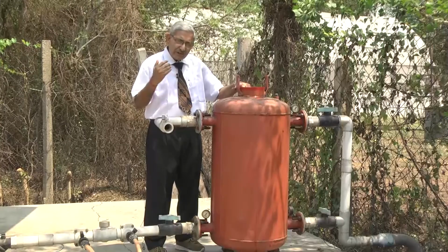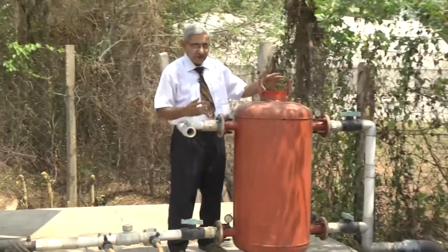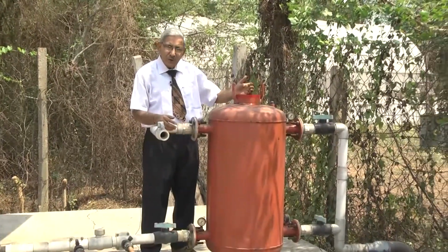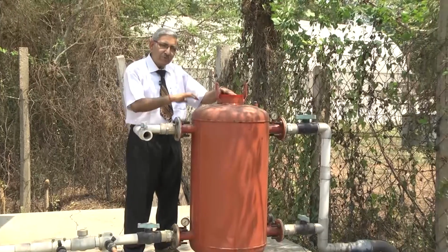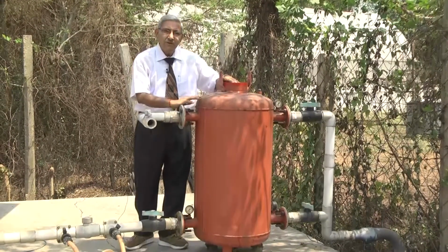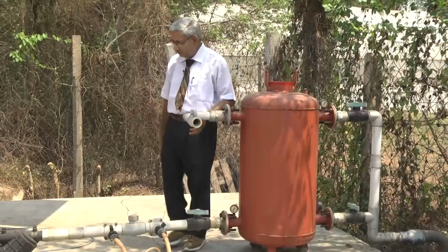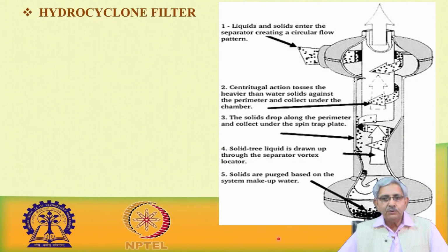Now, if even after that we see that the pressure difference across the filter is still too large, then we have to replace it with new sand and a new grade of the material. Let us come to the hydrocyclone filter.